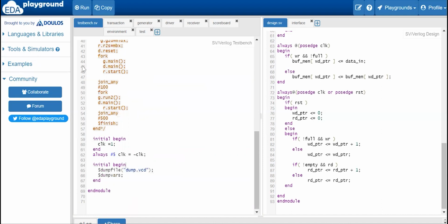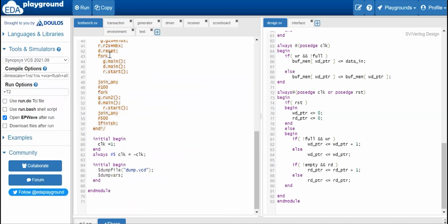So this is how we write the SystemVerilog test bench architecture. For every program we will follow like this only, according to your functionality and variables. The small difference is the scoreboard logic. Scoreboard logic will be changed for each one. So I'm running the program now. You can try with different examples. Take a small example like a flip flop, or you can generate for a combinational logic circuit.